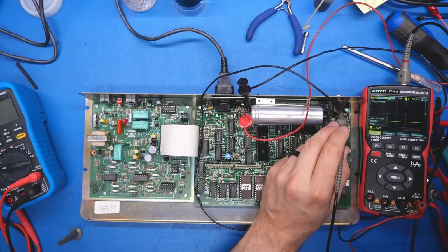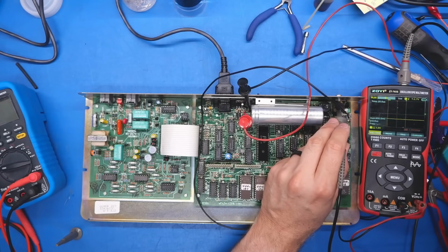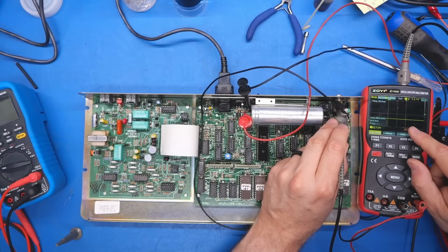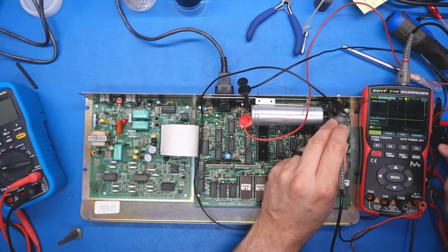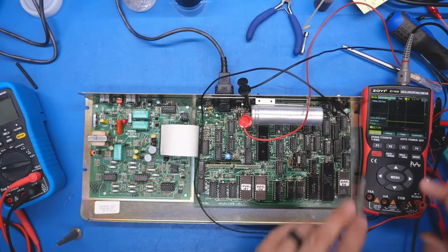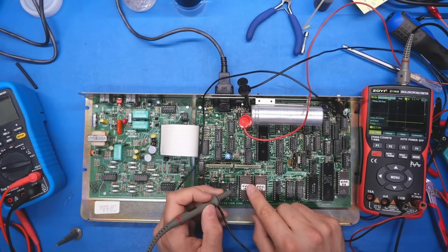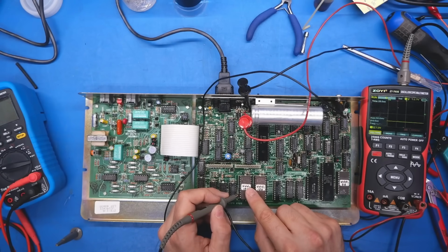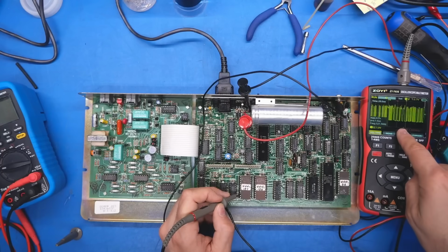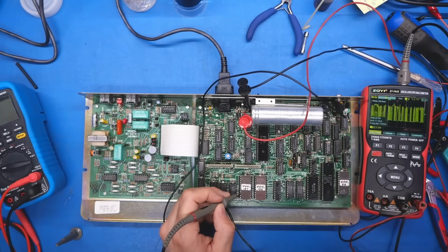Let's do our first check in scope mode. Let's check the video output. Nah, it's doing exactly the same thing. We're just getting like the 800 millivolts on the video output. So the system is powered up, but I'm surprised by the lack of clicking, and I also don't know what's going on with the CPU. It looks like it's running code just like it was before.